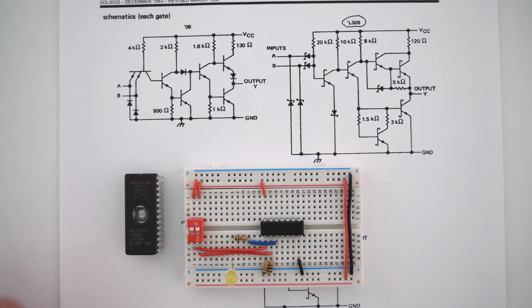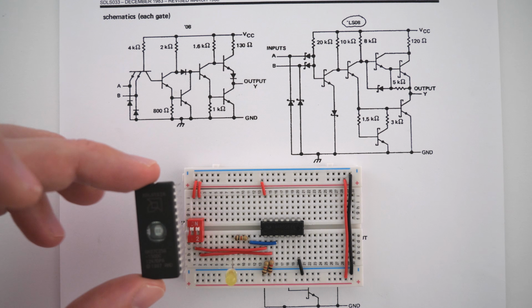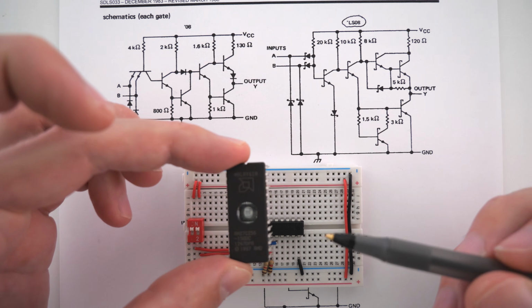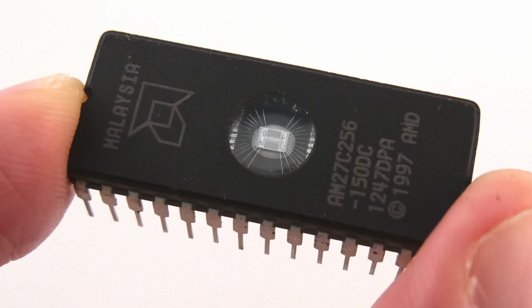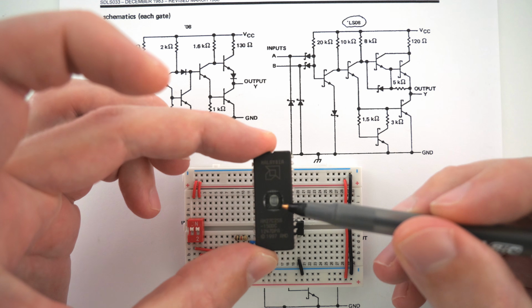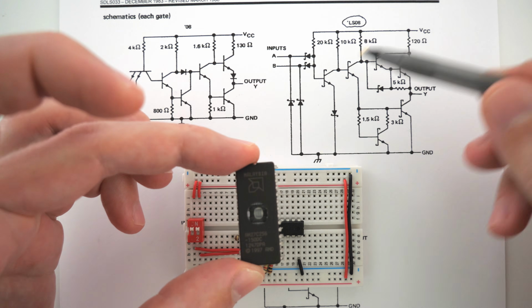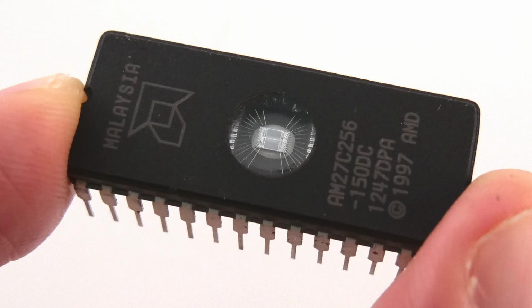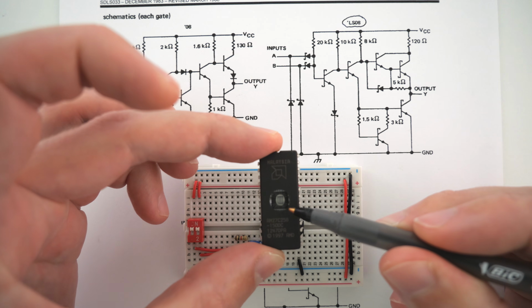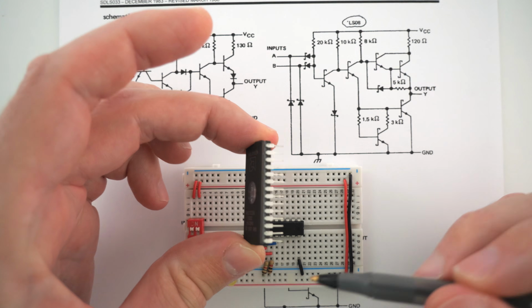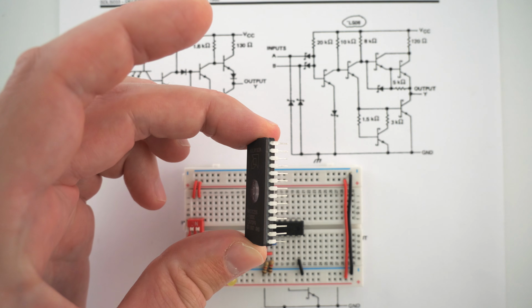circuits. And we can see how these circuits are built within the integrated circuit, because this particular integrated circuit has a viewing window. And you can see at the very center there's a silicon wafer. And on that silicon wafer, all of these different components are placed through a series of microfabrication processes. And then you can see that there's a whole bunch of wire bonds going to that silicon wafer that connect to all of the pins on the outside of the integrated circuit.